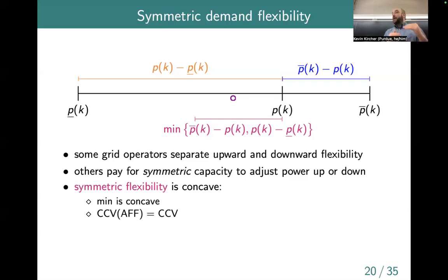And if it sags too far, then you have rotating machines that are basically synchronized to that 60 hertz frequency that, basically for their own protection of equipment, would begin to trip off. And that's actually how cascading power outages sometimes can happen. Frequency sags a little bit due to undersupply, and then a generator for safety reasons says, oh, I can't handle this, and trips offline. Now your supply is even lower and your frequency sags even more. And then other trip offs kind of tend to happen.